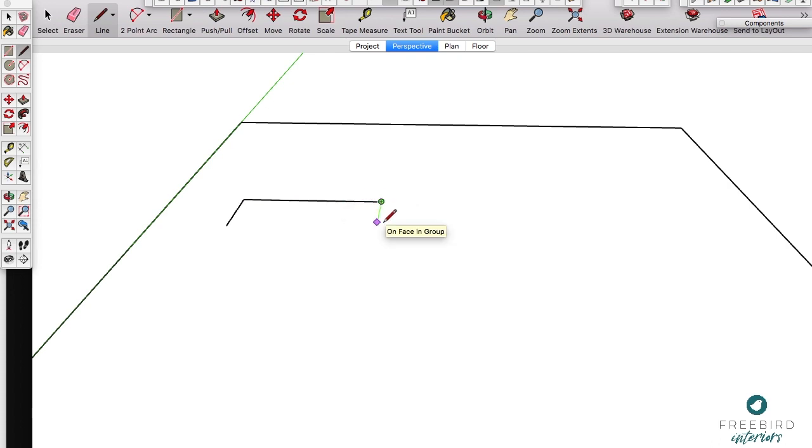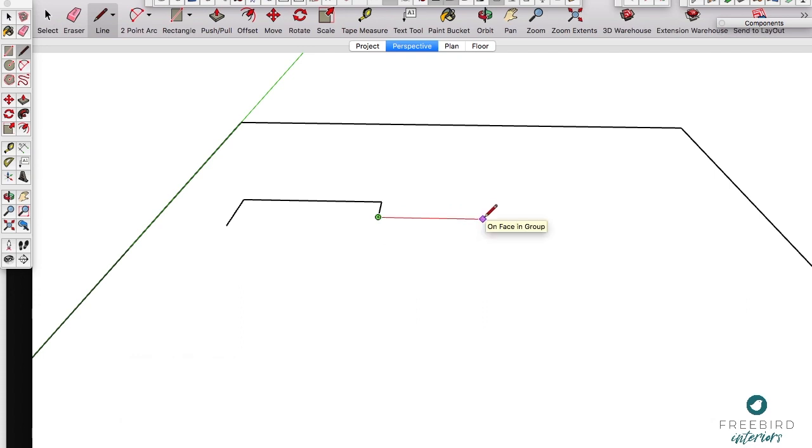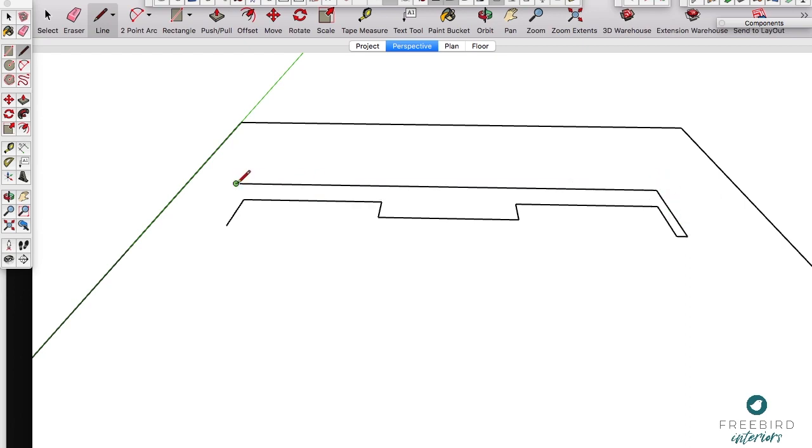So I've got my first alcove width, I'm typing that in, you'll see at the bottom right. This is the depth of the chimney breast. And I'm inferencing, which is using the axes. You see how it snaps to colours. That's the y-axis. So this makes sure I'm drawing everything correctly at right angles. That's my second alcove, and then here's a projecting wall between two rooms. I'm actually going to draw the second room with a different method using a tool that comes with the Cabinet Sense plugin.